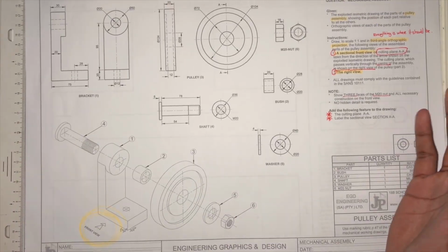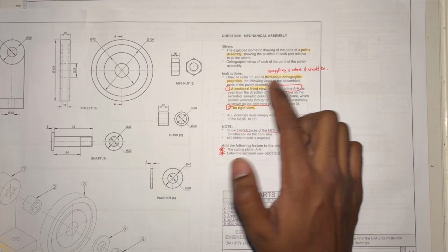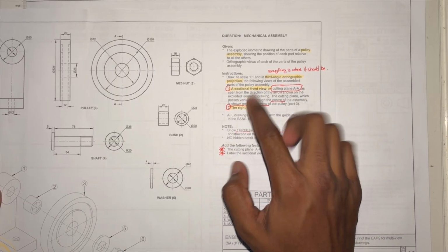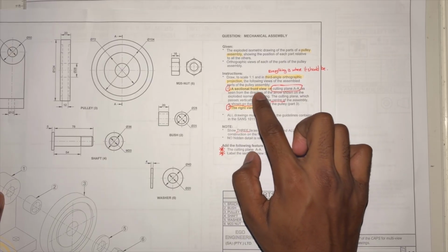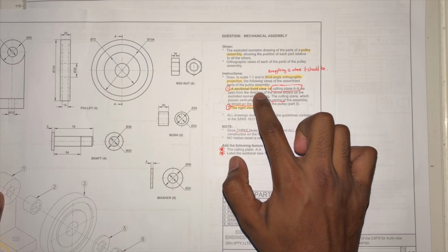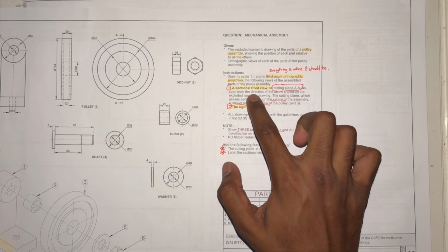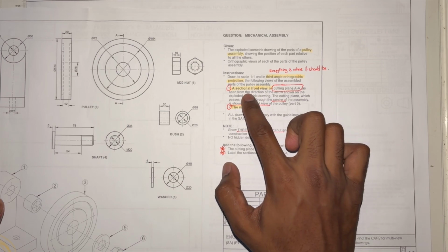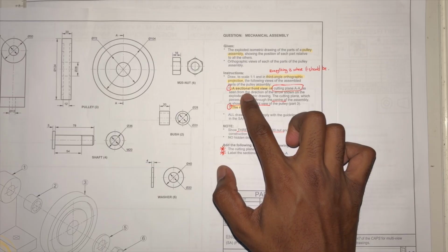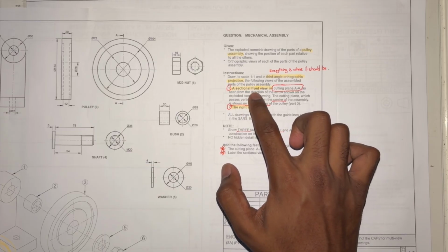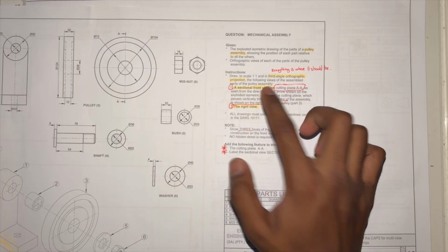Okay, then next question, what should I start with first? Because they want a sectional and a right view. So which one do I draw? Now, I tell my students to draw the sectional front view or the sectional, whichever view is sectional, draw that first. Okay, reason being, it holds the most amount of information. Okay, so it requires quite a lot. Because it's a sectional view, you have to draw every component because it's being cut.